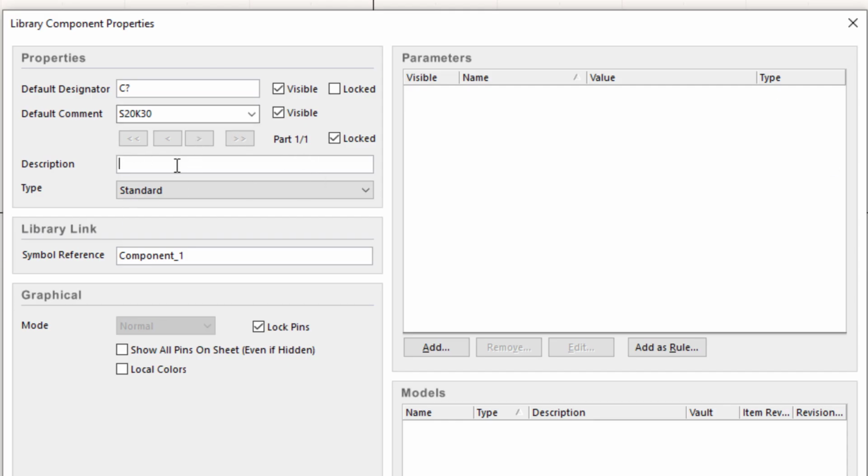So this one is a 30 volt MOV, and something descriptive, like 2000 ampere peak current, and this is in a 20 mm dia disk type. So something like this description you should put, so that during design of your schematic you will easily be able to locate the voltage, the current rating of this MOV, and easily drag and drop it.